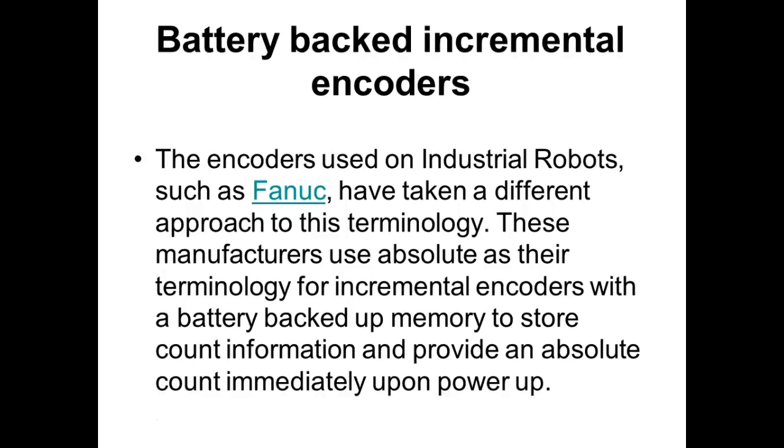I think ABB, well, it's got batteries in there. Batteries dead, power out, right, you're screwed. Well, you're not really screwed. It's the robot. Now, what we have to understand is a lot of your controllers use solid state memory that has to have batteries. That's where you get screwed. The batteries are dead in your controller, not your robot, in your controller, and you lose power.